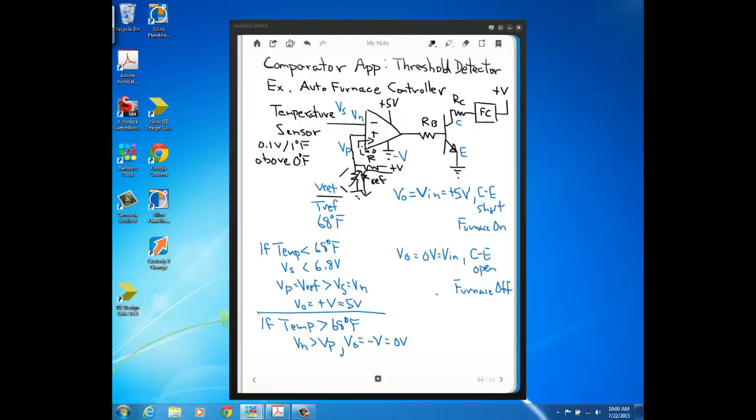Okay, so that was a couple of tidbits of important information. Another one, and we talked about this a little bit when we were going over the basics of a comparator, is when the input voltages of a comparator are close to each other. Okay, when Vp and Vn are essentially equal. And remember, it's hard for voltages to be exactly equal for any significant amount of time, mainly due to thermal effects, so you'll get fluctuation in voltage over time.